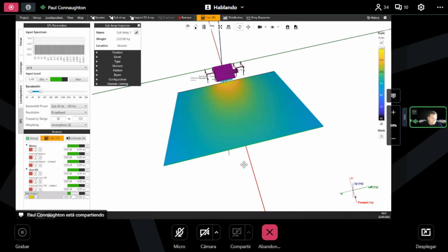Underneath this, we can also set whether we want to see our metering in dBu, dBV, or VU, depending on your preference. We then also have a bandwidth toggle, so we can select the minimum and maximum frequency that we would like to include in our SPL calculation. Alternatively, we can choose from one of the 5 bandwidth presets. These are commonly used bandwidth presets that we have defined based on what clients and individuals tend to want to produce as documents for production or clients.